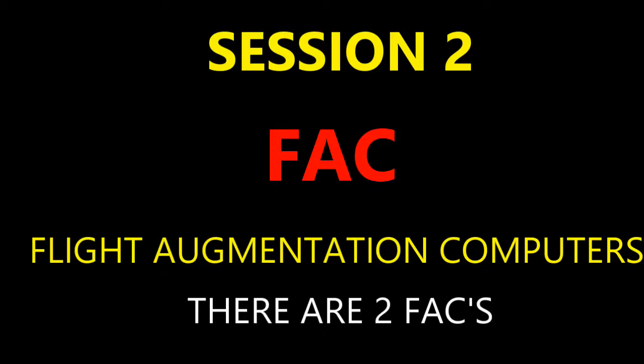Just to make sure that the system's working right. Okay, so for example, if you have a test for the -3 and -6 pages, when the predictive wind shear function is active, you want to make sure of something. You want to make sure there's a certain message, and this is on the EWD, your engine warning display. You want to make sure that it says REAC WS DET. Okay, so REAC WS for wind shear, DET, detection fault message. I want to make the distinction between that and another one that's called the WINDSHEAR DET FAULT. That could be there, but that's not the one you need to make sure is there. It's the REAC WINDSHEAR on the engine warning display. If you go to the status page, you want to make sure the same message is there. Okay.